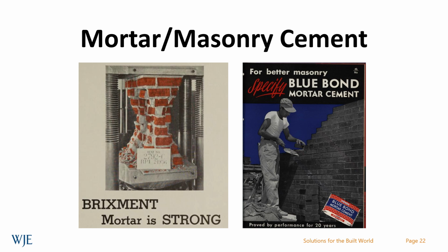One of the common misconceptions during this time was that harder mortar was better mortar. And while the mortar technologies were advancing in order to develop masonry cements and other types of pre-bagged mixes, getting past this notion that harder mortar is better was critical to this time period and some of the issues that resulted from it.